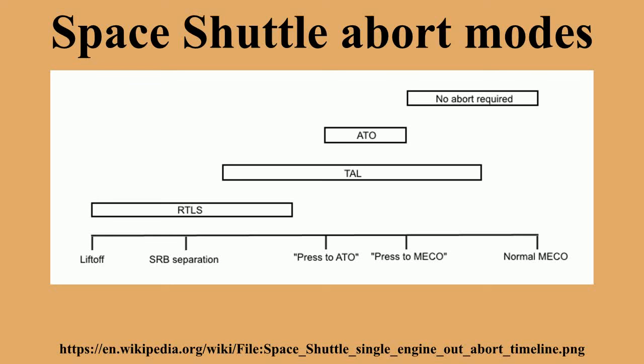Space Shuttle abort modes were procedures by which the nominal launch of the NASA Space Shuttle could be terminated. A pad abort occurred after ignition of the shuttle's main engines but prior to liftoff. An abort during ascent that would result in the orbiter returning to a runway to a lower-than-planned orbit was called an intact abort, while an abort in which the orbiter would be unable to reach a runway, or any abort involving the failure of more than one main engine, was called a contingency abort. Crew bailout was still possible in some situations where the orbiter could not land on a runway.